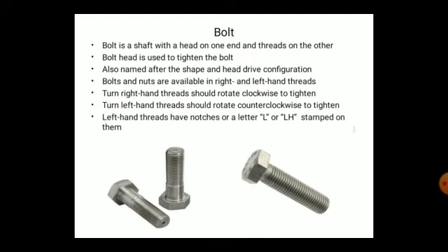Bolts and nuts are available in right as well as left hand thread. So these two types are available. In most cases we normally use right hand threaded bolts, and in some special cases you have to use the LH, or left handed thread, and this left handed thread is mentioned on the bolt head.